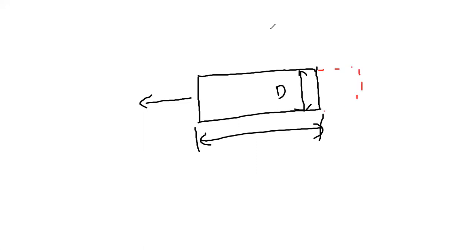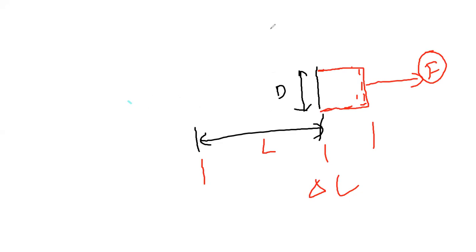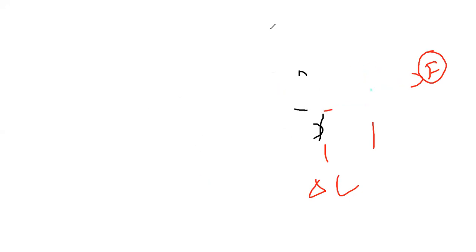The length of this particular one is L, and here I have applied a force, so its length has changed. Can I consider this change in length as delta L? Yes. Delta L is the change in the length due to the applied force on this strain gauge. That is what we were representing in the previous figure. Now, how these changes take place, I will try to elaborate.